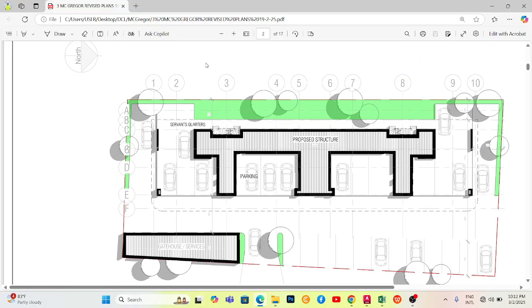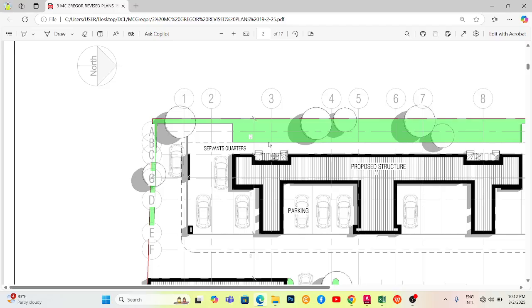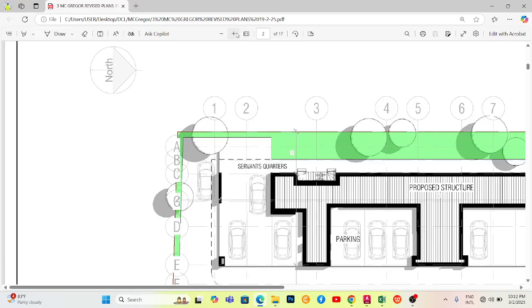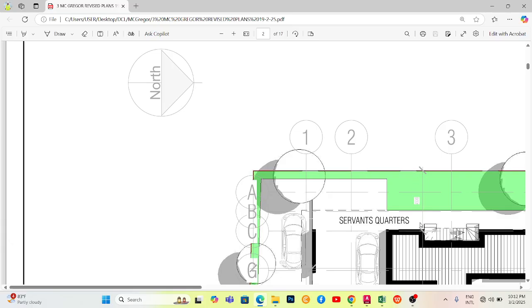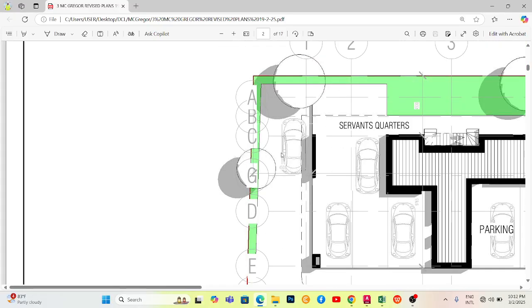So I'm always looking after the offset because it is very, very, very important. Let's look at this for example. So this is 4.5 here from the wall fence to the building itself. This is 4.5. So I will look for that on both sides before I start taking my offset.